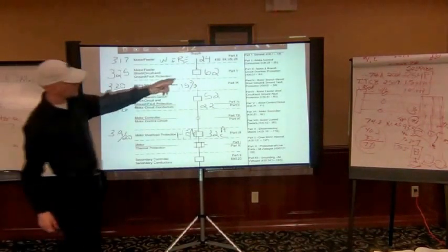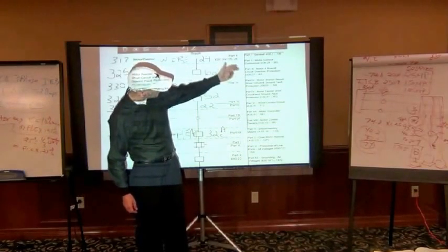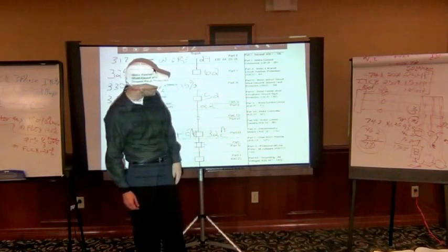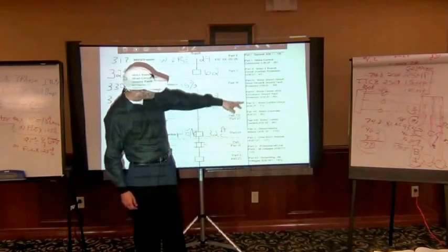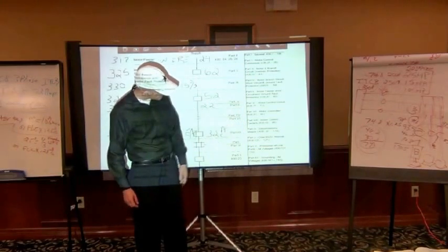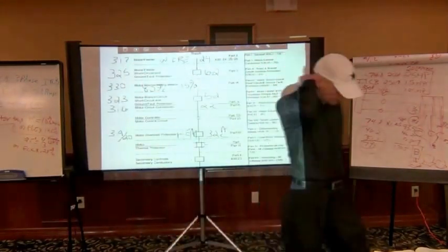You've got your part 1 general, wiring in part 2, your overload heaters in part 3, part 4 is your short circuit ground fault, and part 5 is your feeder short circuit fuse and stuff. Motor controllers and motor control centers, MCCs, disconnect means, and then down there you have your over 600 volts and your table values.